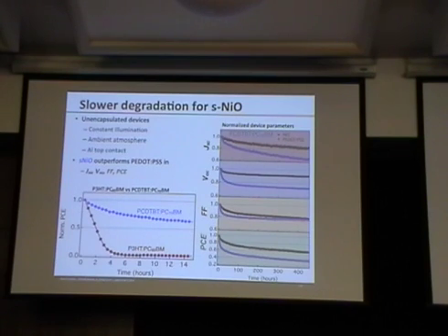Now, in addition to that, as was pointed out, PEDOT:PSS is also just a bad actor, right? It does a lot of things we don't like. And while PCDTBT is a much more stable system than the P3HT:PCBM, which is what's shown in here, for the PCDTBT, if we compare the nickel oxide and the PEDOT device, we see that all the device metrics across the board are better, and they're better for longer. So this, I would argue, also supports that when we've used the nickel oxide as this contact, we've done a better job of removing charge carriers from the active layer, which is what we want to do in a solar cell. Any questions? Everybody's on board now? Okay.